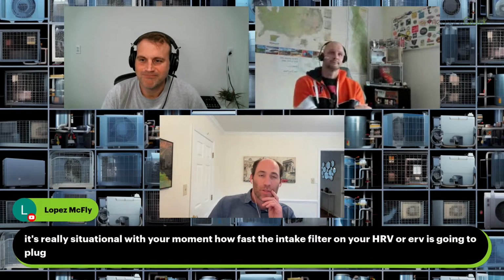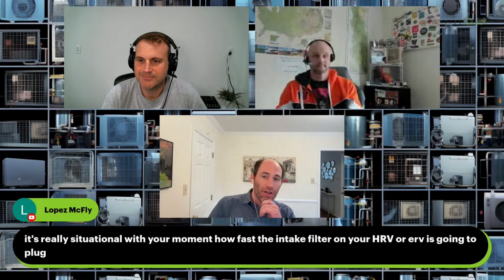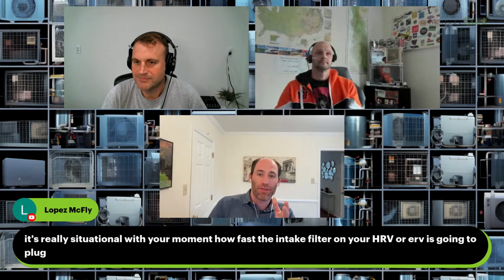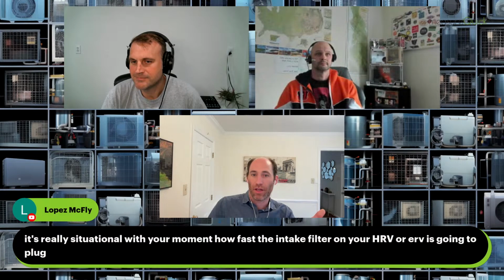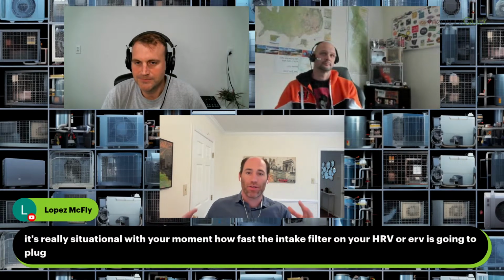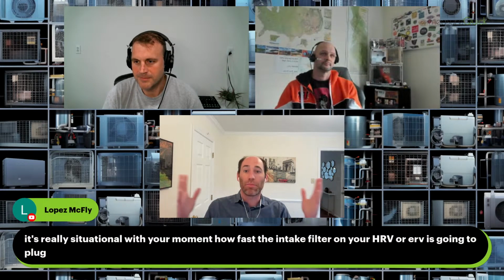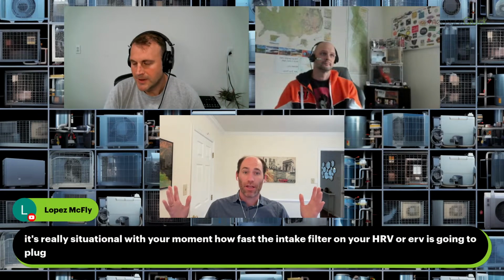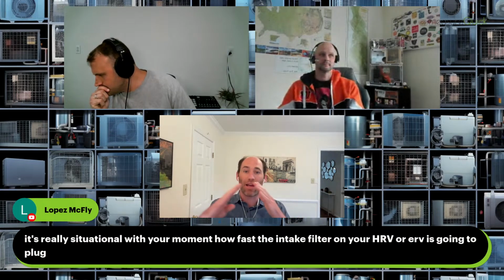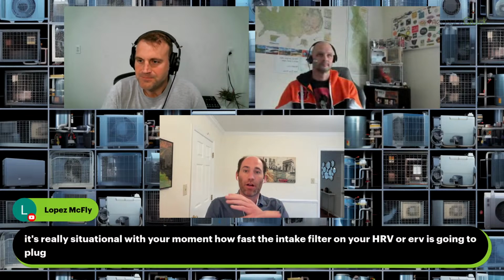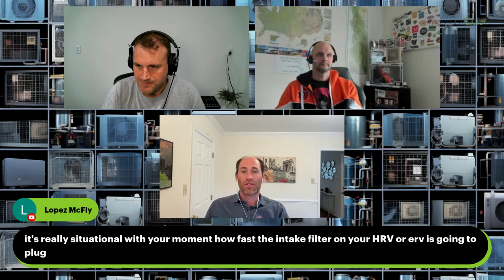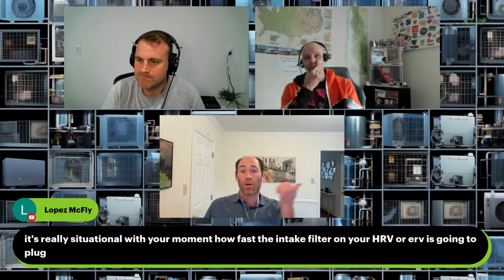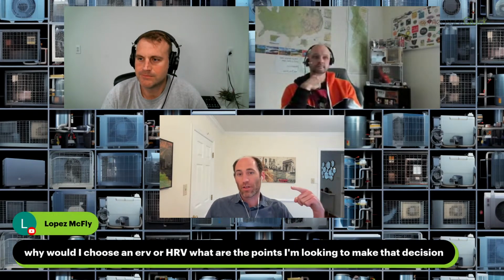Yeah. So in our climate, we're definitely using ERVs, because the basic difference is that an HRV has a heat exchange core. It can be like aluminum, okay? You've got two channels of air passing over each other. Let's say in the winter, you're sending warm, stale air outdoors and you're bringing in cold, fresh air indoors.